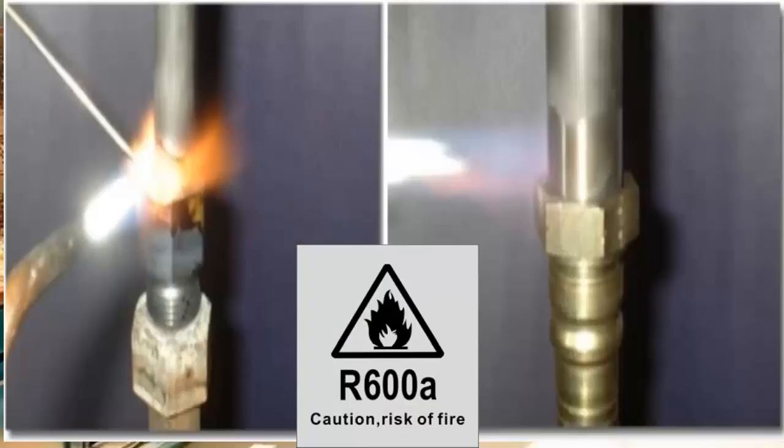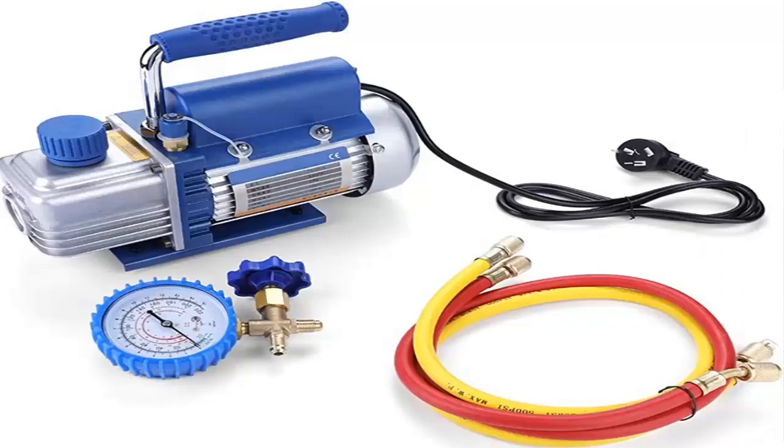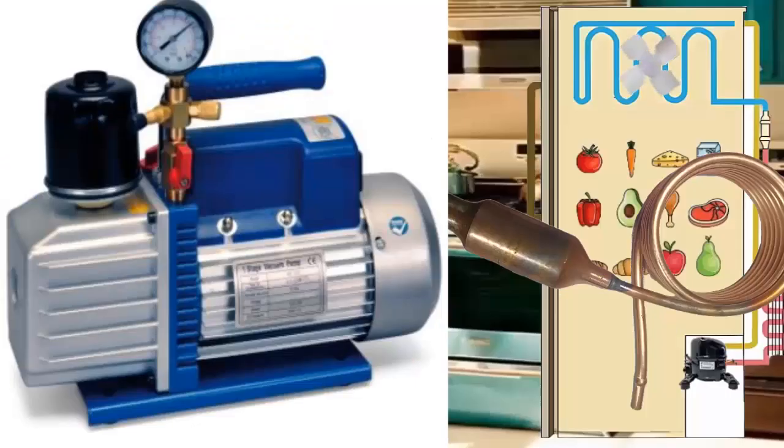The main risk when performing corrective maintenance on equipment with R600A occurs when performing any welding. In this regard, it is recommended not to carry out this procedure without having previously completed a complete vacuum of the equipment with a vacuum pump, carrying out this process for several minutes, with the gas expelled outside. And paying special attention to possible accumulations of R600A in the capillary tube.